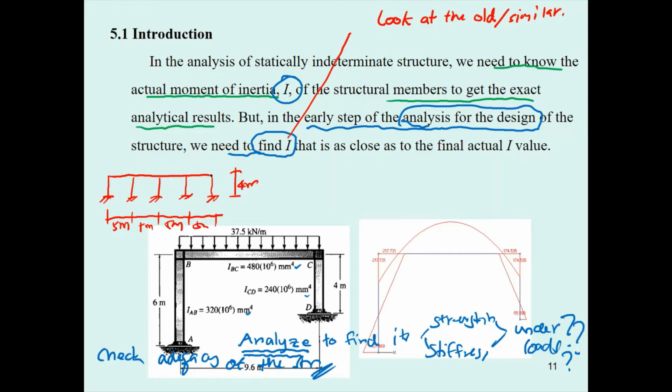You may go to some building that is similar to this and measure the size of the beam and the column, to be used as a guideline to determine the moment of inertia.